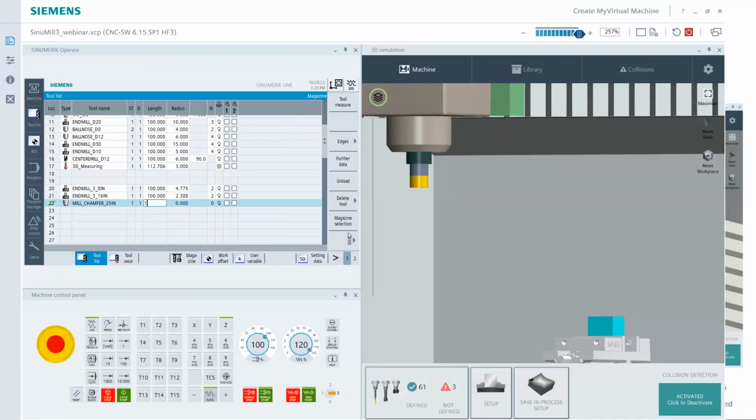The trick here is this diameter. This happens to be, in this case, radius, but this would be the size at the tip of the tool. We need to know that if you're using cutter comp, because that's what we would comp. So I give it that size. So let's say for argument's sake, it's pretty small, 0.5 millimeters, right? Some flutes if I was doing feed per tooth.